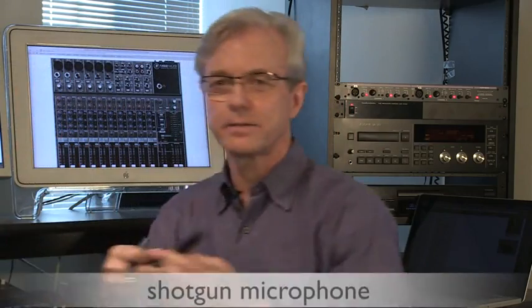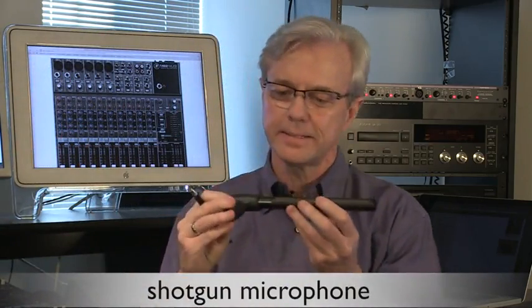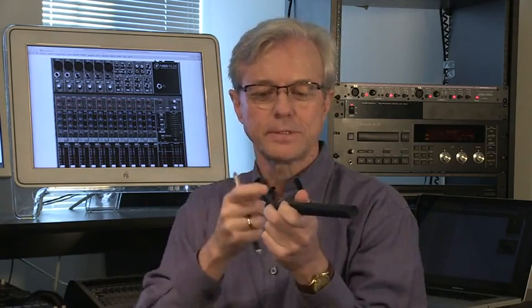Another specialized microphone is referred to as a shotgun microphone. So this is a Sennheiser shotgun microphone. You'll often see these in video or film applications where there'll be someone usually with some kind of pole and they will have a shotgun microphone. And what this does is a very narrow cardioid pattern. It allows for a pickup of only a tiny range of space. So you can point this particularly at someone far away and you will get nothing but that sound and it will cut out any sound around that.